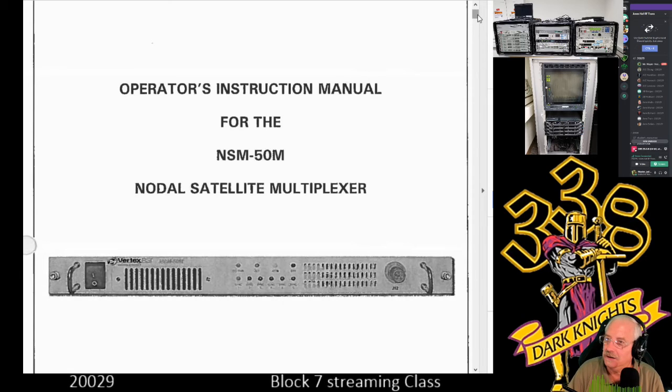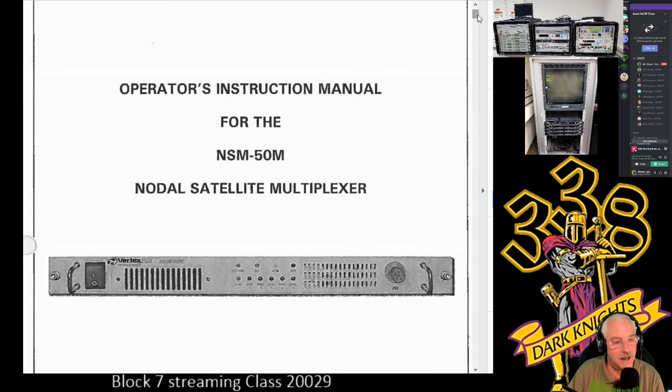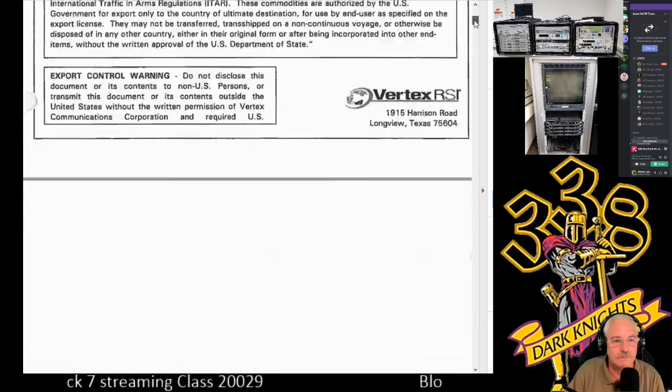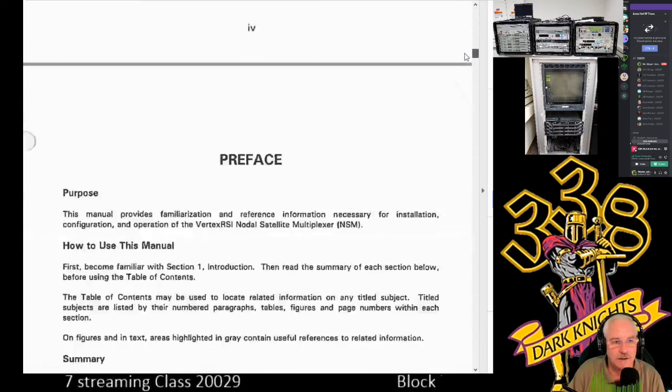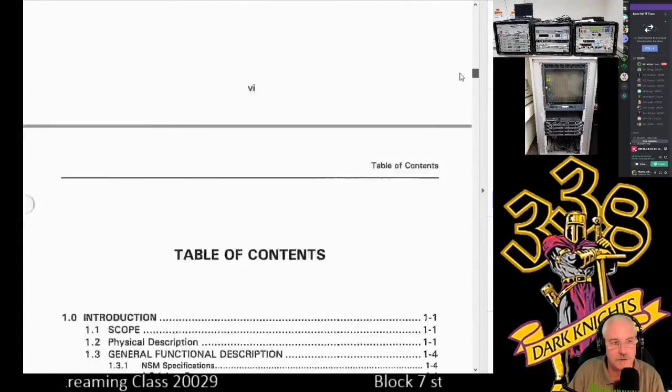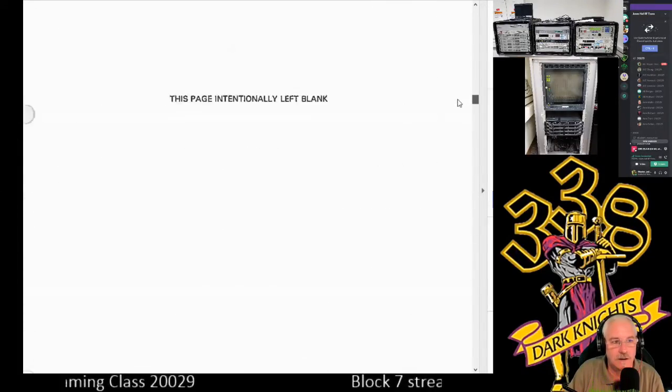The biggest thing is when you are doing your checks and everything is said and done through the GUI, the big one is the top right LED. If the error light is on, it ain't working. You've done something wrong with the programming. So I'm going to scan down here. You'll notice we got some warnings and so forth and so on.